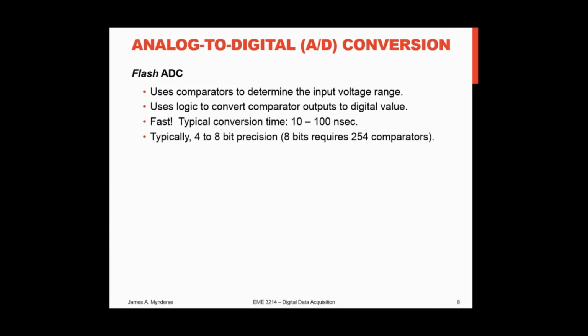One type is the flash analog to digital converter. Basically, you just set up a whole bunch of comparators. If I have my voltage in, and I say that I have a comparator here, an op amp essentially, where the input here is, say, 1.25, and that goes in there. If it's greater than 1.25, that's on. Then I compare it to 2.5, and I compare it to this voltage, I compare it to that voltage. And I just have all these comparators. And it's fast. It's essentially instantaneous.